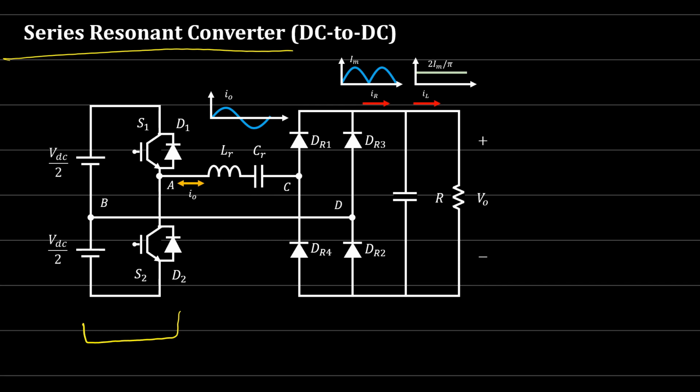Of course, if you want to increase the voltage on the output, you can use an H bridge, no problems. You get double the output voltage at points A, B, okay? And here I replaced the two capacitors with two power voltage sources, also just for simplicity, okay?